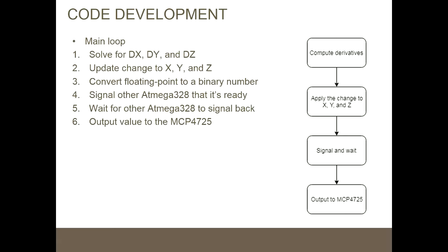I did try to use the default multiplication for the Atmega on Atmel Studio, and it definitely didn't work because I'm working with 32-bit numbers, and the microcontroller is 8 bits by default. Like I said, I didn't go with 64-bit double precision because of overhead. I'm working with 32. We're on the boundaries of the Atmega not being powerful enough to compute these numbers, but luckily they were able to compute the numbers.